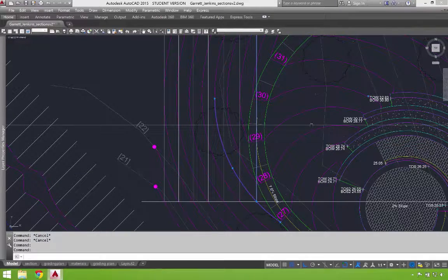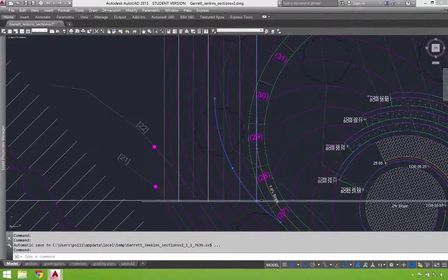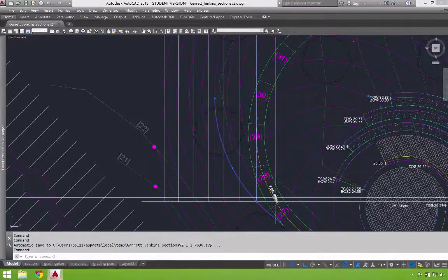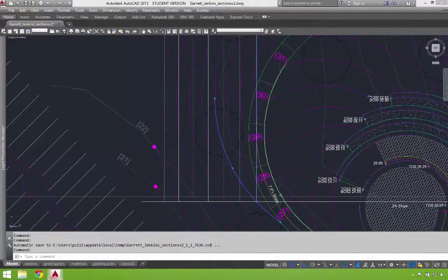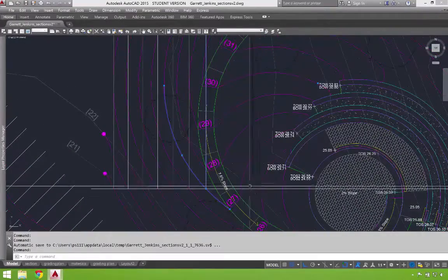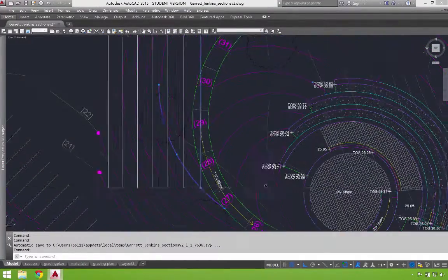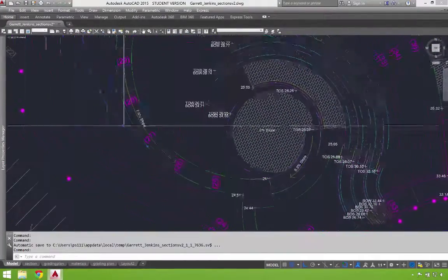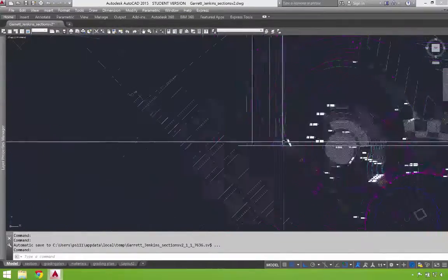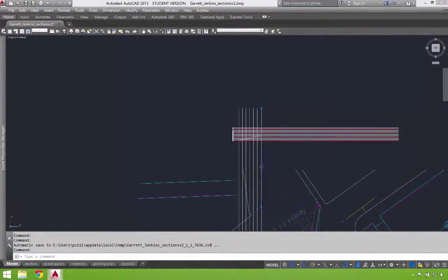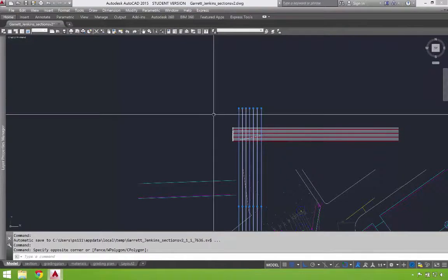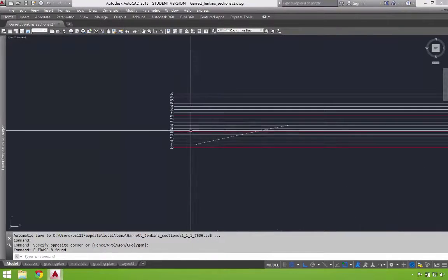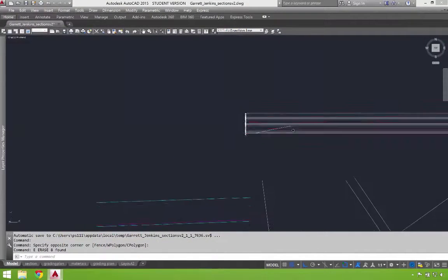Now what you're going to notice is that I ramp up and then move back downhill in this particular situation. The top of this path actually represents the highest part of my slope before I start moving back down to the 27, 26, and 25 contours, and even lower than that to the 24 contour. So the first thing I'm going to do, once I've figured this out, is that I don't want too many guidelines in my way. I'm actually going to delete these out of my scene. You can see that my section cut line is still here.